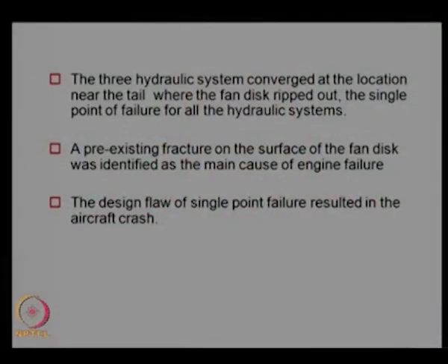So in this case, the pre-existing fracture on the surface of the fan disc was identified as the main cause of engine failure. So that was the main cause, because the fan disc had some problem, but the design flaw of single point failure resulted in the aircraft crash. The main reason why the aircraft crashed was the single point where all the hydraulic systems were converging, and from that point onwards it was a single point failure situation.